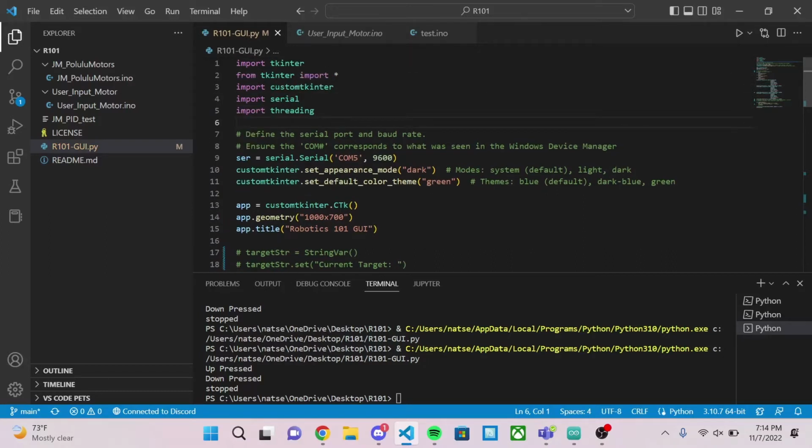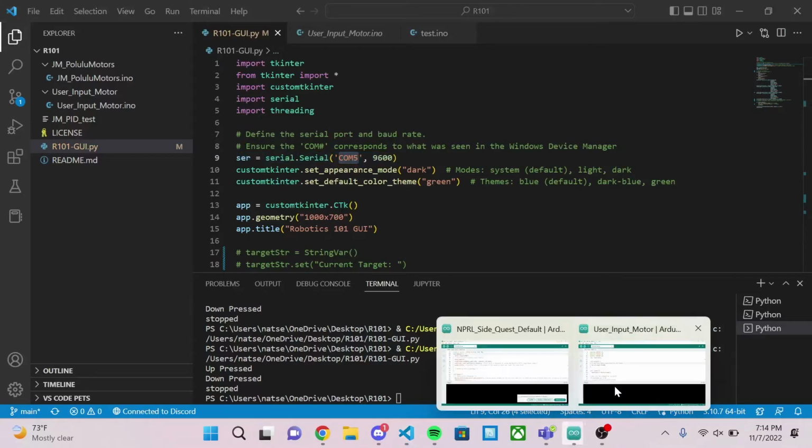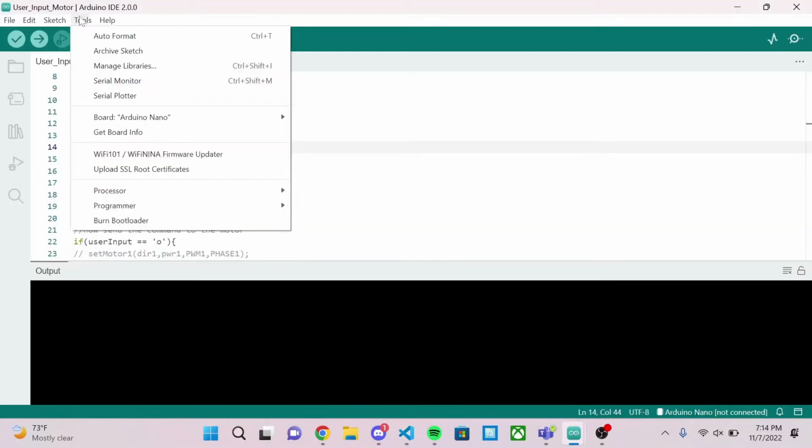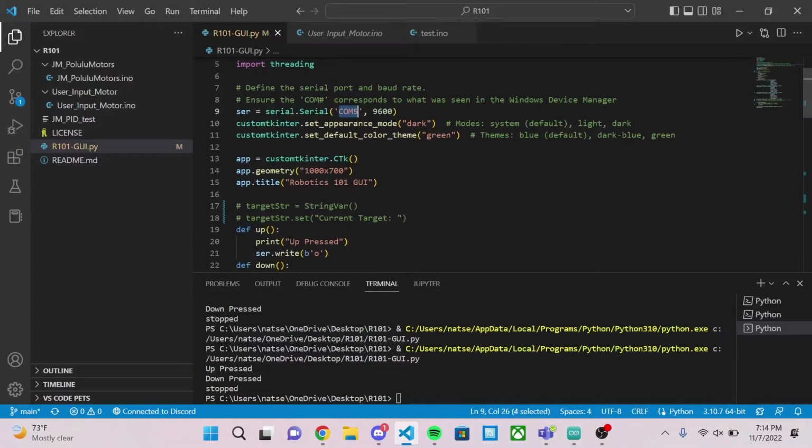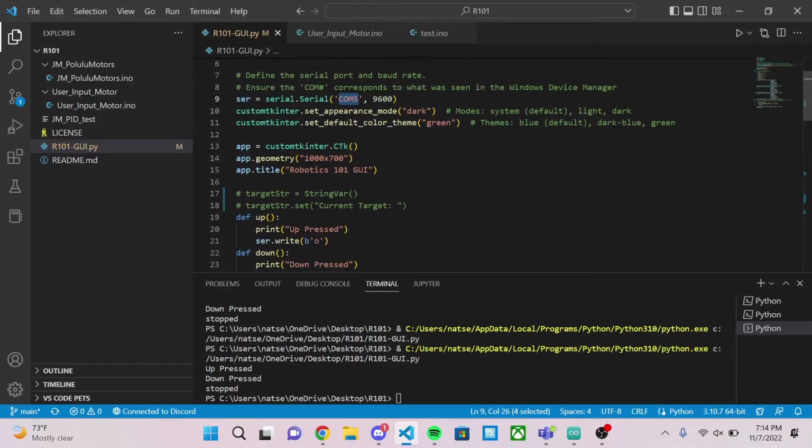And in order to communicate with the Arduino, you first need to initialize where the serial is. So for me, it's COM5, but you can find it by going to your Arduino program and going to Tools and finding your board information. Or Device Manager, yeah, like Richie said.